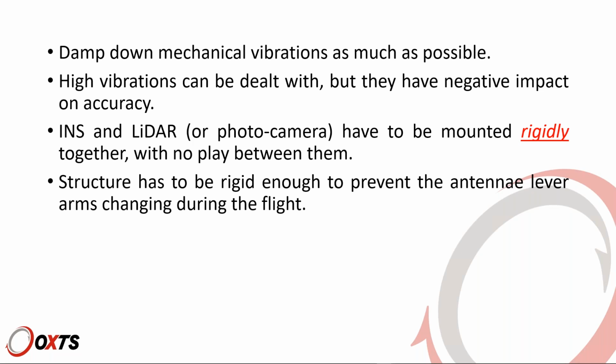Mechanical vibrations are one of the biggest issues with the drone's installation. So you need to do your best to damp them down mechanically. At the installation and mounting stage, make sure that the INS is not vibrating too much. High vibrations can be dealt with, we will see in a minute, through appropriate configuration, but they will have a negative impact on accuracy.